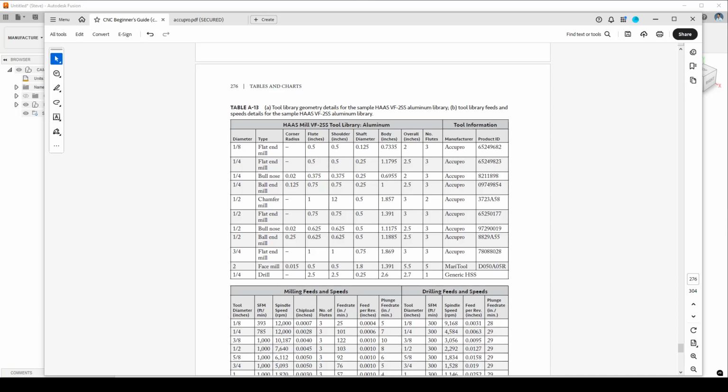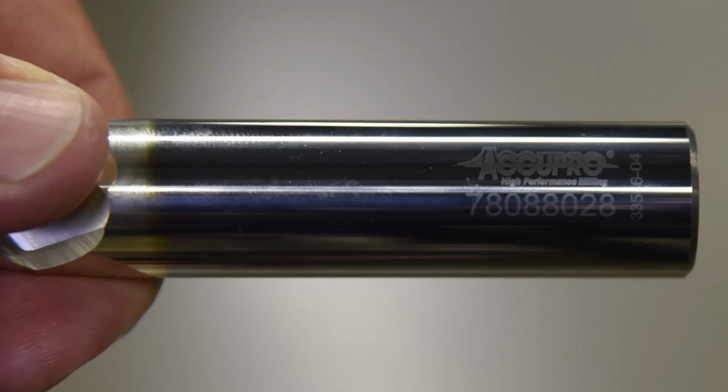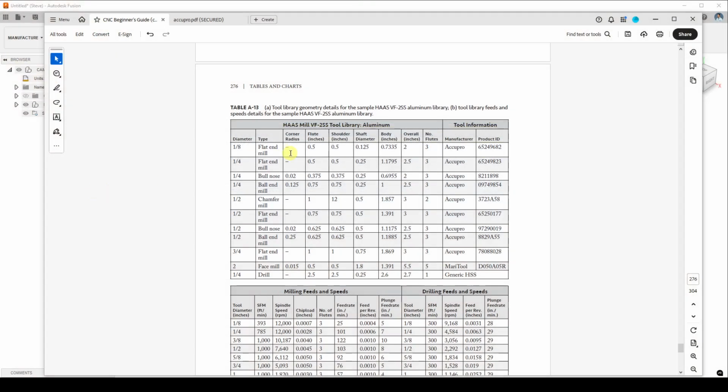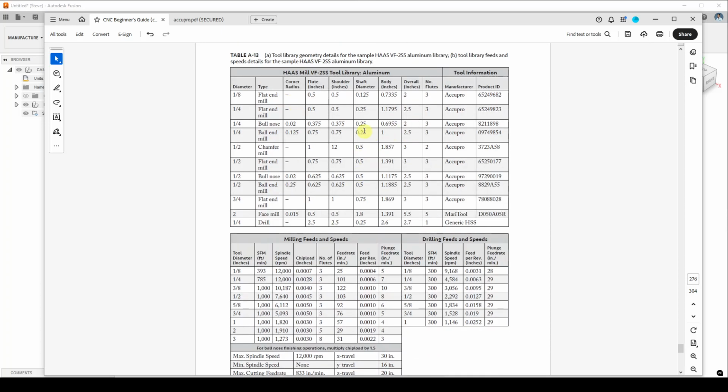Now, finding the right tool geometry is really important, and a lot of times you can get to that on the tool itself. It'll be printed with the manufacturer, their logo, and then the number which defines that tool. You can use this to look up information from the manufacturer, and they'll usually give you really specific geometry for the tool, as well as some recommended starting points for speeds and feeds. So here in this table, what I've done is I've worked up speeds and feeds that I have tried and I know work on a Haas VF2SS.